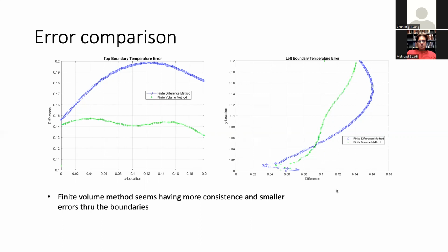However, I think the small deviation from the finite difference method is really because of the limitation of the method itself. Due to the heater we have, it really has a curved surface, and the finite difference method is not really the best method to solve the problem with a curved surface. And for the finite volume method, if we want to minimize the error, we can probably use an irregular shape volume around the wire. That way we should be able to minimize the error.